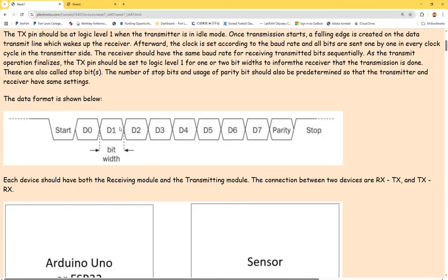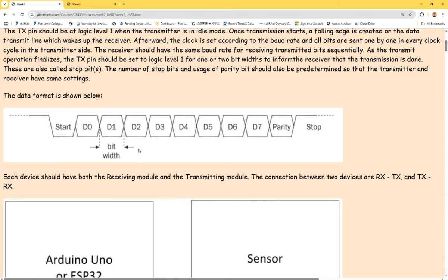What are the 2 port names of the UART port? Rx, TX, yes. How do you put down the transmission line at the beginning and put up to logic 1 at the end? You just put it down, right? Oh, the TX pulls it down at the very beginning and pulls it up to 1 at the end. Okay, and then it moves to the modules.